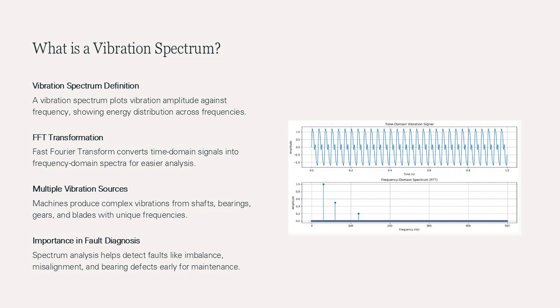components responsible for vibration. This approach is the cornerstone of modern vibration analysis and condition monitoring programs, enabling early detection of faults like imbalance, misalignment, and bearing defects. Understanding the spectrum is critical for diagnosing machinery health accurately and preventing costly failures.